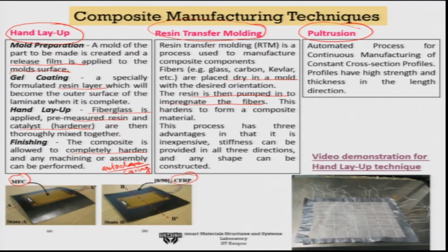The only thing here is that the fibers are in all the directions. So, here you can artificially create anisotropy. Okay. So, here you can create anisotropy, that means by changing the fiber angle, etc. But here, generally you cannot create anisotropy. So, this is, I would rather say, homogeneous and isotropic. Some applications need this kind of thing, where you need to provide fibers along all the directions, because possible sources of loading can be from all the directions.